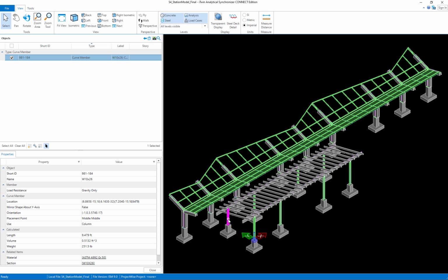You can see here I have a wide flange column, and again I asked them to assign the appropriate material properties to those columns. Now, that being said, do I have to take a look at these material properties once I get into STAAD? Yes, I do, because although they were given different material classifications, I still want to make sure other pieces of information such as modulus of elasticity and yield strength of steel are appropriate, and that type of information might not be contained in your BIM model. So I'm going to take a special look at things like sections and material properties once they come in.